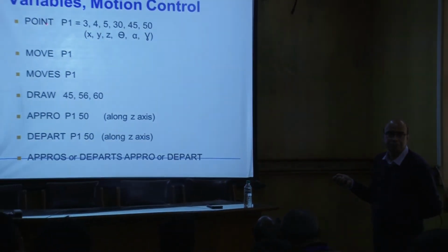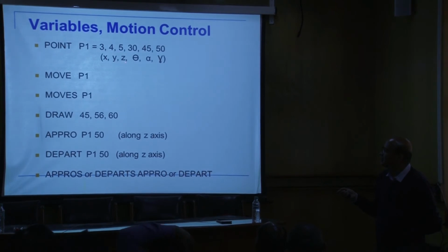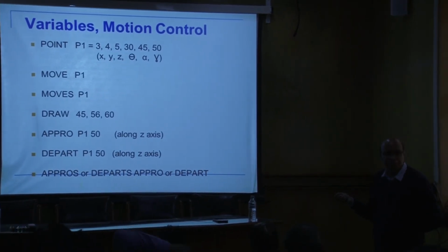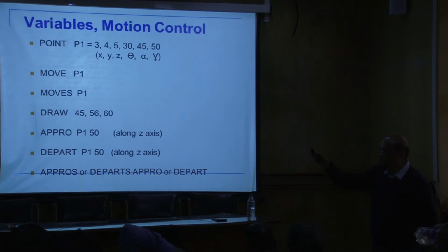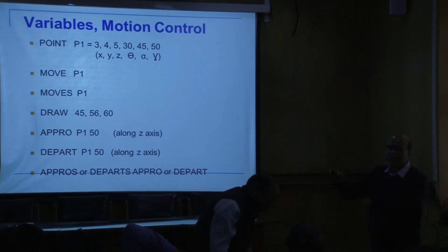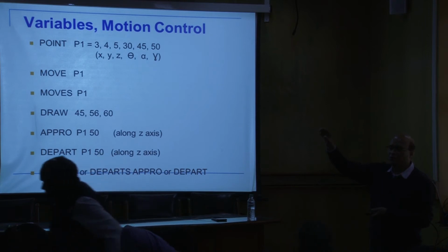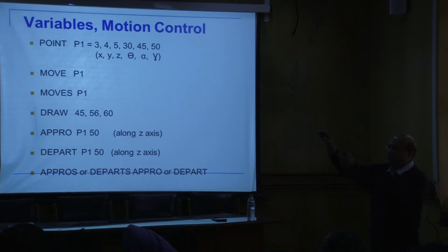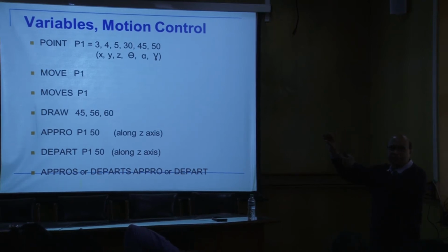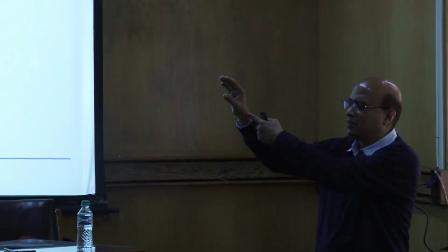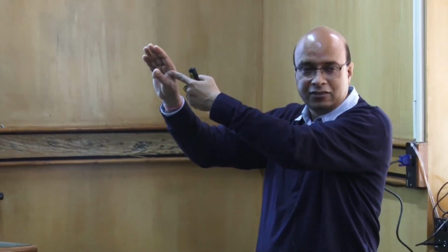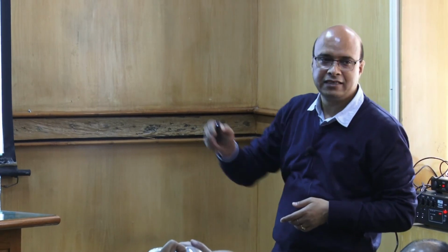This is the coordinate of the point P1: X, Y, Z in terms of the base coordinate frame, the 0 frame. This is the orientation of the end effector. So the robot has a hand, right, like this. If I simply say XYZ here, the orientation could be anywhere. The XYZ is still the same. So in my hand also, if this is my XYZ, then it could have a different orientation with the same XYZ. So you have to define the position and orientation. This is giving me the orientation. This is giving me the position of the end effector.